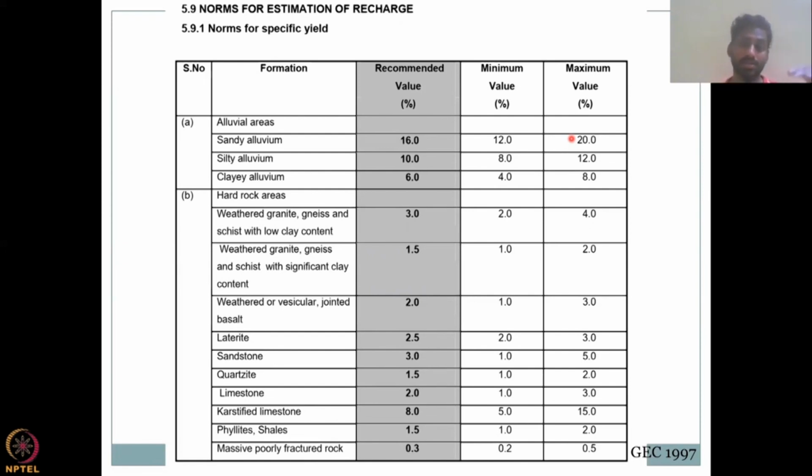Please understand that recharge is a process from low groundwater level to high groundwater level. Water goes in, groundwater recharge happens. The water level is pushed up, that is recharge. What is discharge? Your groundwater is high, it is pumped out, so water is lost, and the level comes down. Or it can naturally come down because it is discharging.